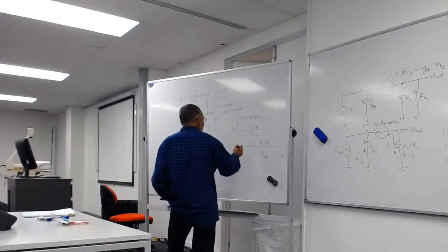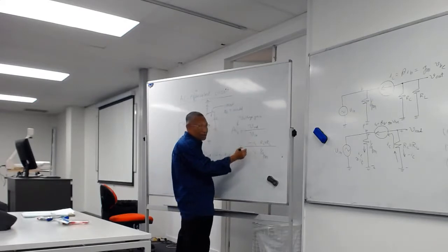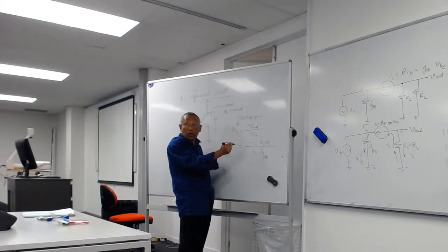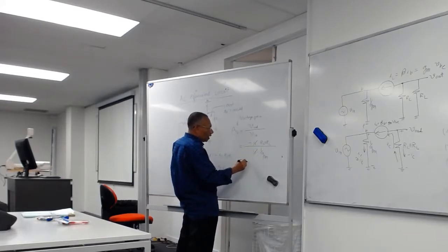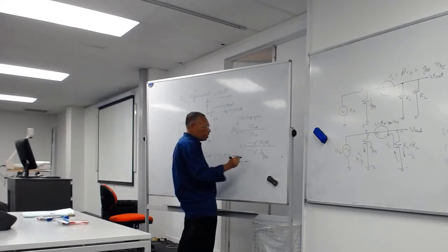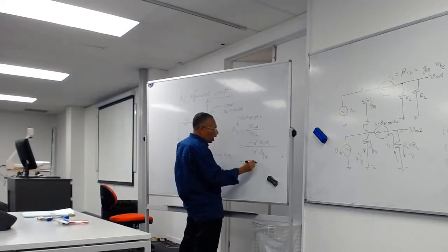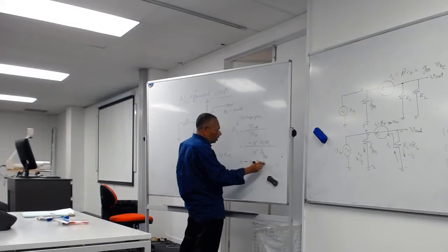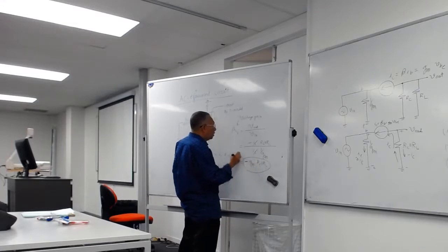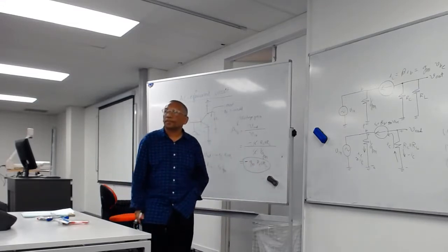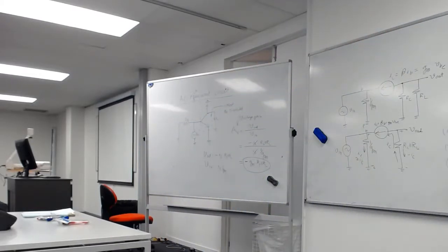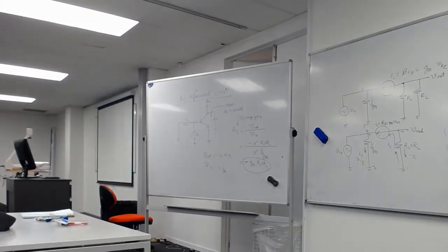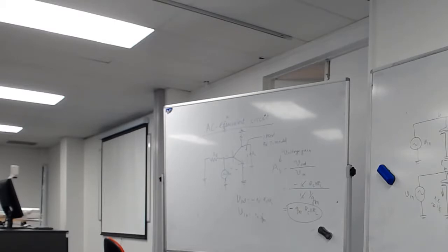Okay. So now what we do is that we cancel. Can we cancel IC top and bottom? Okay, so we'll do it. And then this is equal to minus GM, which will go upstairs, GM into RC in parallel with RL. Okay, so this is your voltage gain. So this is your voltage gain. Okay? Small signal voltage.